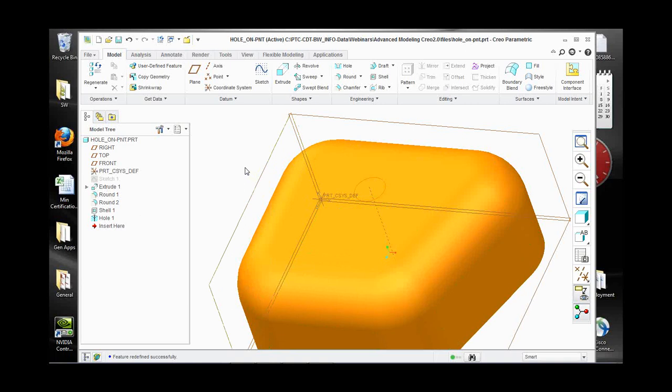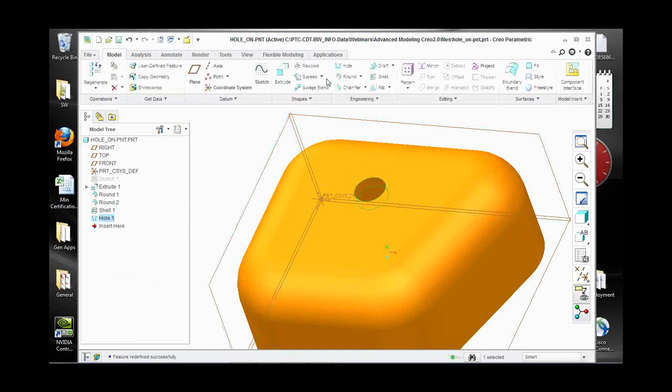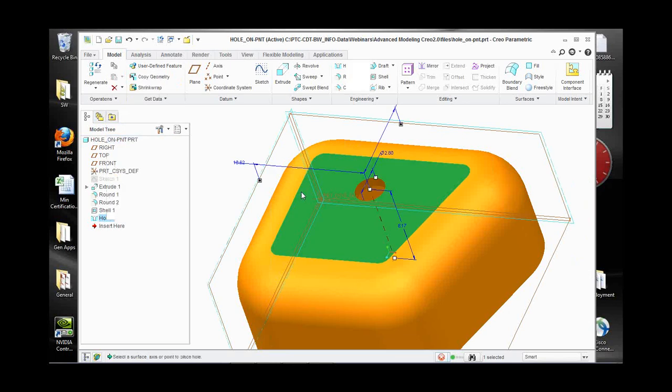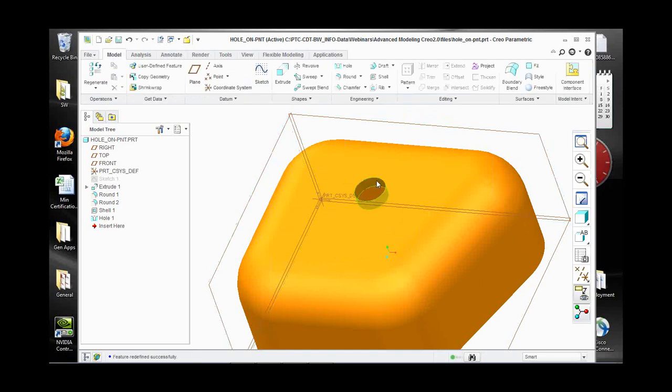Now, can you leave it that way? Obviously not, because really the only thing that exists is the sketch. So when you are done working on your model or you're finished with your design, you would come back into this hole, do an edit definition, uncheck this, and you only have that regeneration one time, not the 30 times that you regenerate throughout the day, okay? So it is what is called the lightweight hole feature, and it is based more than anything else on being able to regenerate especially large patterns quicker with just a click of the button. You say OK, and then again, if I would have picked it, you would have seen just the outline instead of the hole itself. This is what is called the lightweight hole feature.